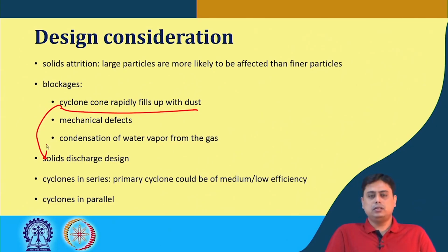If the operation is happening under pressure, any outward leakage, although it can increase the efficiency, can release pollutants that contaminate the nearby atmosphere. Or if the operation is happening under vacuum, then any inward leakage means the deposited particles can be re-entrained in the cyclone zone.